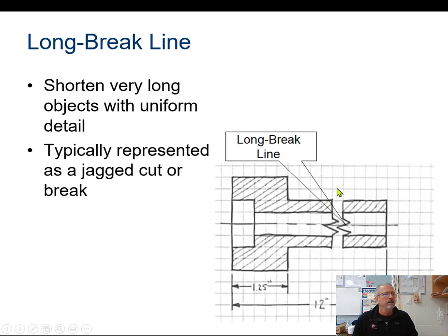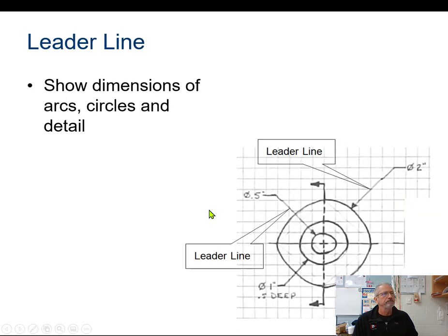Okay, long break line. Here you can see it's marked as 12 inches long, but this is not actually drawn at 12 inches, right? So right here we can see each one of these is a quarter of an inch, right? So this is 1 1/4. That certainly is not 12 blocks. That's certainly not 12 inches long. So what they do is this area right in here is all the same. So they just say, well, we can fit it on a smaller sheet of paper if we just use these break lines and we don't have this big long piece that's going out there. So that's a long break line. And an inventor will do this.